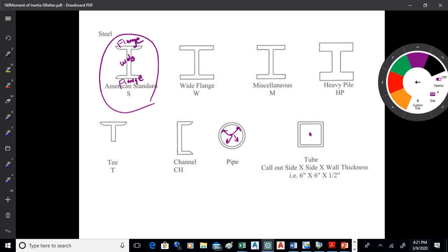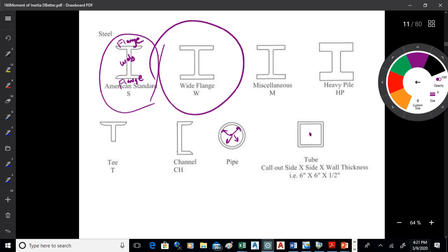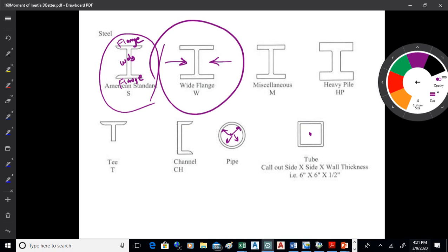But they've changed. They use wide flange beams now. And one thing that a wide flange has that an American Standard does not is strength if it's loaded laterally from the side. Normally, when we're putting beams in, we think about them being loaded vertically, down. But now we look a little bit at the side. Why do you suppose here in the Northwest we look at sideways loading? Yeah, earthquake. That could be big. Okay, wind and things like that, but earthquake especially. So we want strength laterally as well as vertically now. So wide flanges are the more normal type of beam.